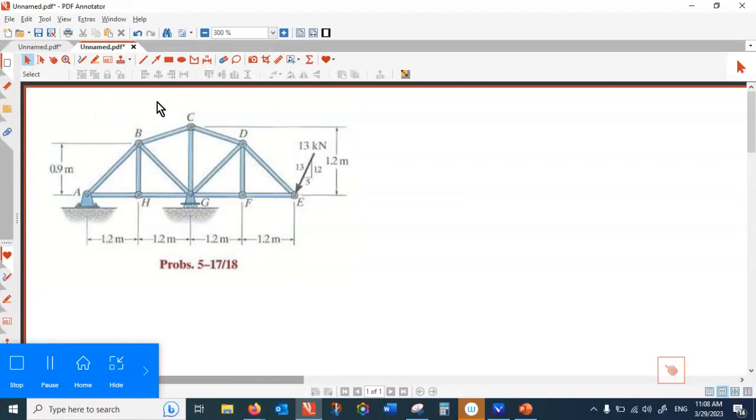If I apply the method of sections here, there will be two free body diagrams, left hand side and right hand side. Which one do you reckon would be easier to use? Left would be easier, right? But that requires finding the reaction at A. I don't think there is any easier solution. If anyone thinks there is an easier one, let's discuss it.